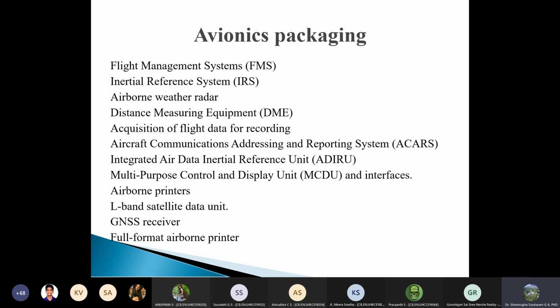gyroscope. So the gyroscope will always maintain this axis, and if the aircraft were to change its orientation, it can always be with reference to this axis which is already set on the ground and carried on board the aircraft using the gyroscope. Okay, so this referencing scheme, which is independent of anything on board the aircraft and is primarily set once for all by consulting space-based schemes for referencing, is called as the inertial reference system. Inertial is because it is non-accelerating.